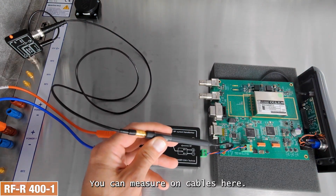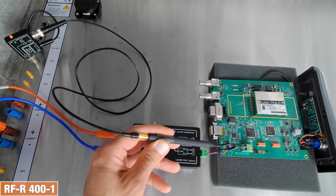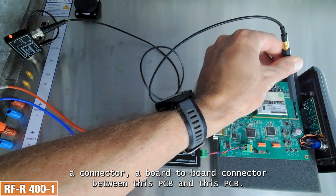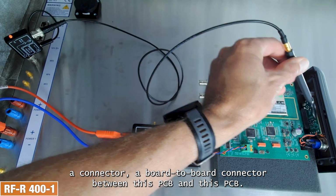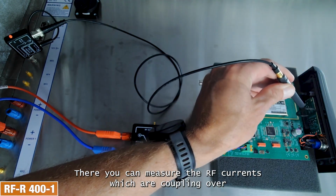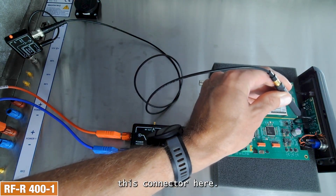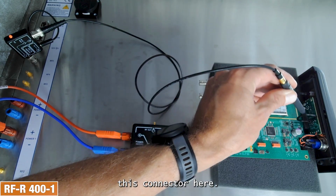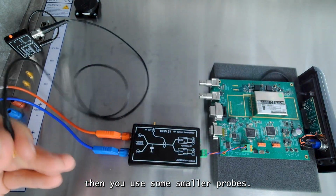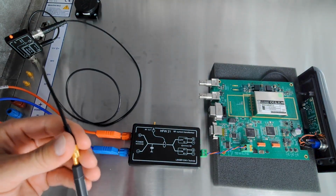You can measure on cables here. Or also when you have a connector, a board-to-board connector between this PCB and this PCB, there you can measure the RF currents which are coupling over this connector. And if you see that there is a problem, then you use some smaller probes.